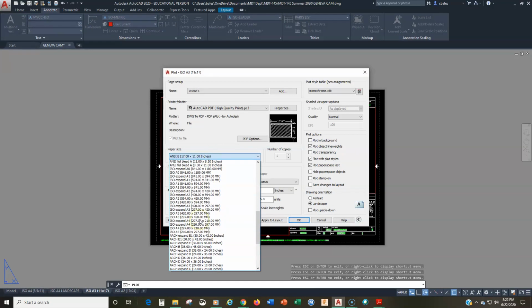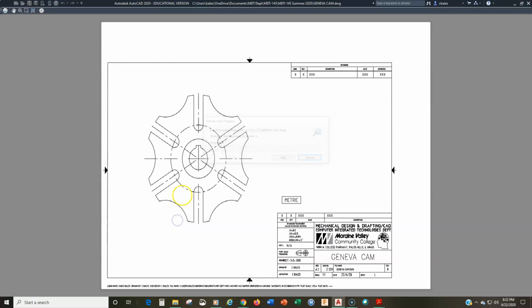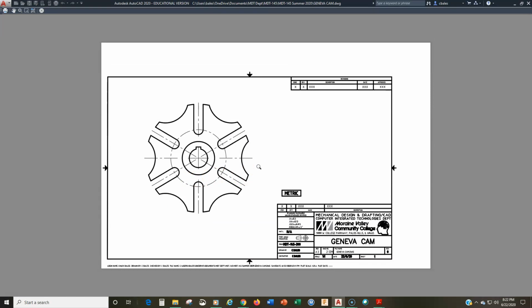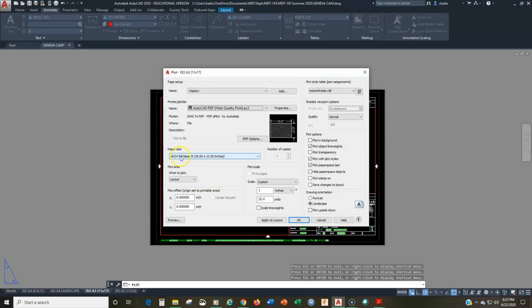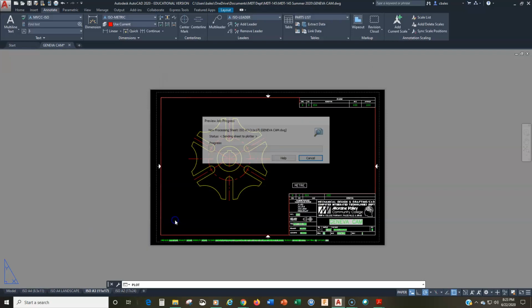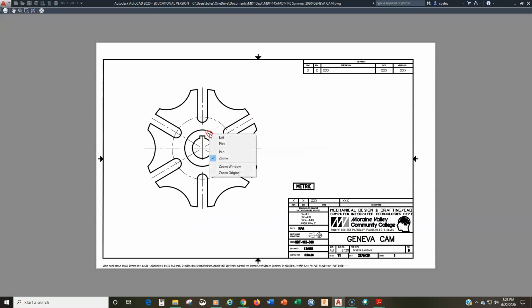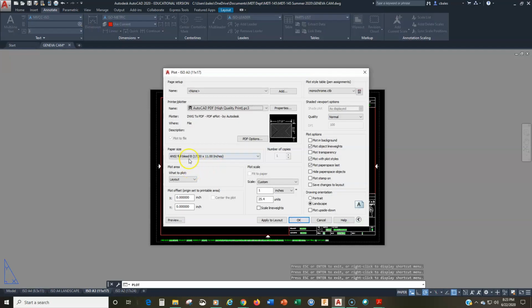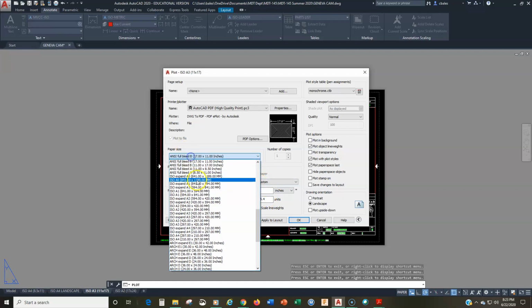Now let's preview this. Whoops, that's not right. I think we're going to have to do full bleed. ANSI B full bleed, there we go. That's better. Okay, so please note, we're going to have to print, whoops, I did architectural full bleed. Let's do ANSI full bleed. Sorry, let's get this right. Preview. There we go, that's better. Okay, so you're going to have to plot it ANSI full bleed B layout, and the scale is going to be custom 1:25.4, which should be done automatically.